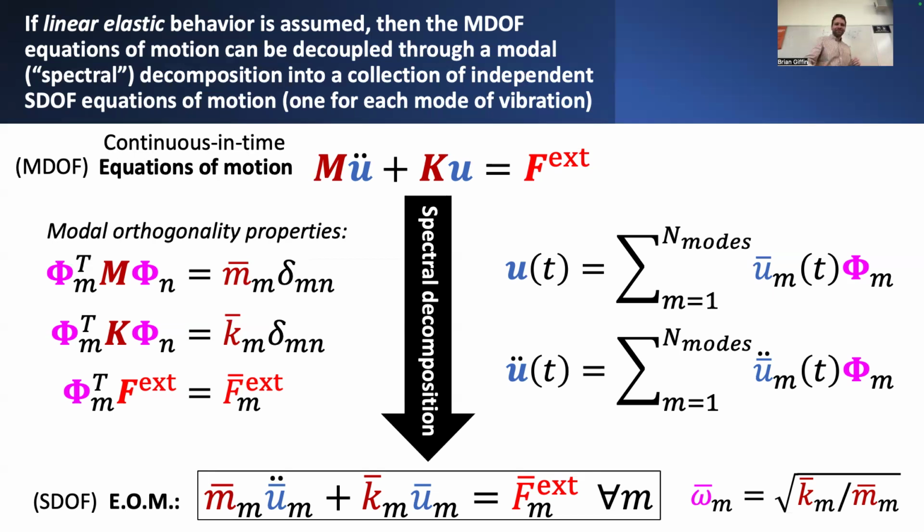They don't interact. So this fundamentally hinges on the assumption of linear elastic material behavior. As soon as you get to nonlinear analysis, large deformations or nonlinear material behavior, it doesn't work. So that's the one thing to be aware of. But assuming that you just want to know the vibration characteristics of the structure, this is a really great way to analyze that.